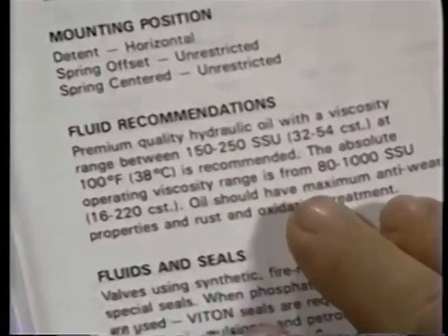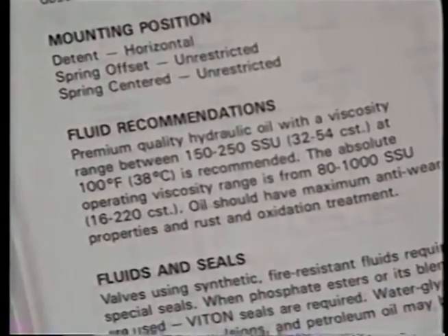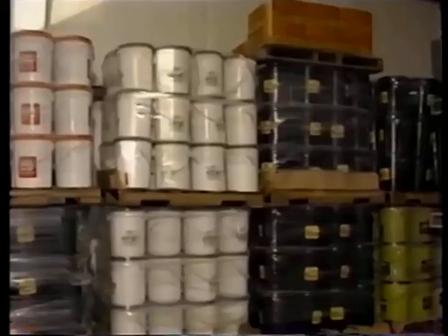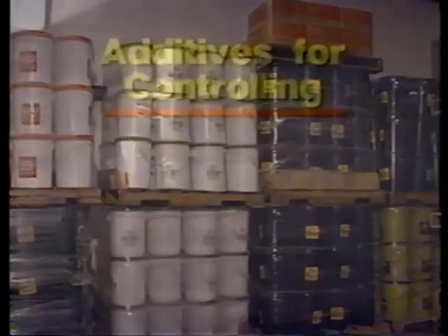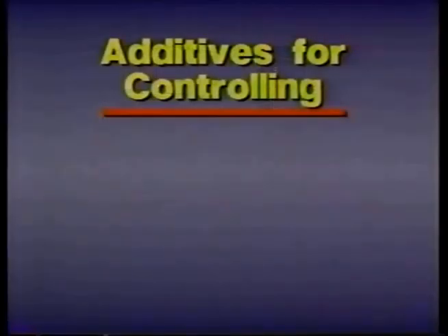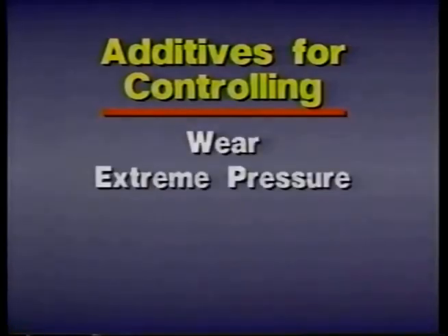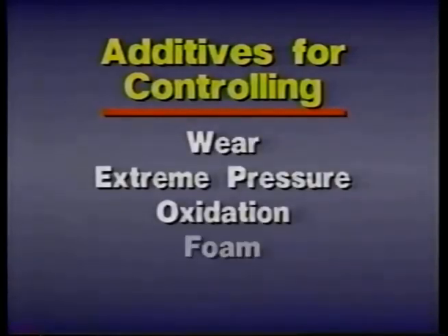Most components of a hydraulic system are designed to operate within a relatively narrow range of fluid viscosities. It is essential that you always make certain the fluids you use match the specifications called for by the equipment manufacturers. As industry's use of hydraulics has expanded over the years, a variety of chemical additives have been developed to handle problems of excessive wear, extreme pressure, oxidation, foaming, and rusting.